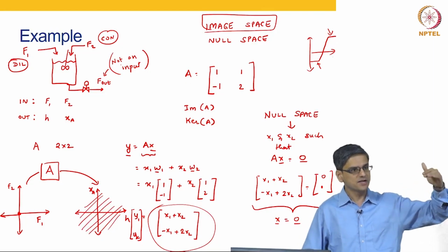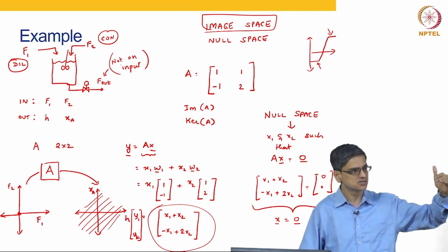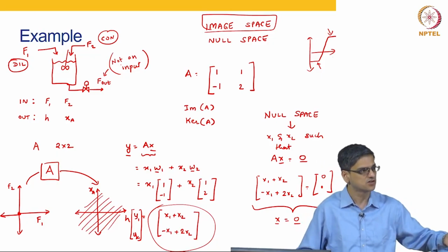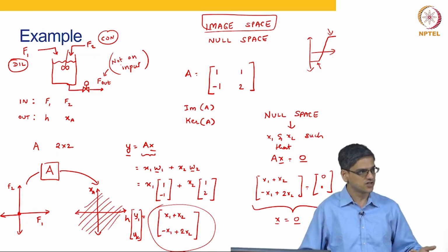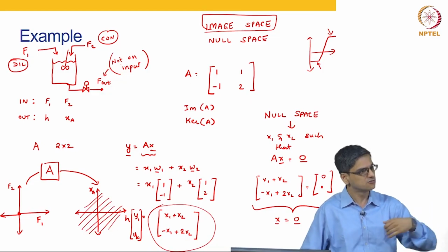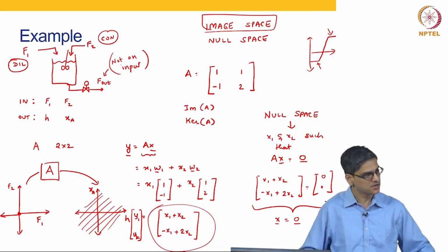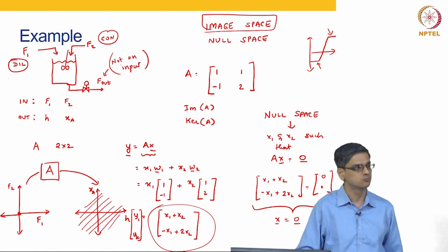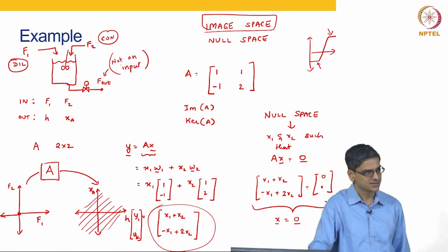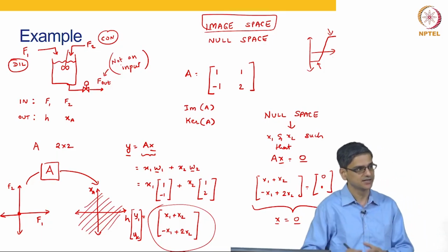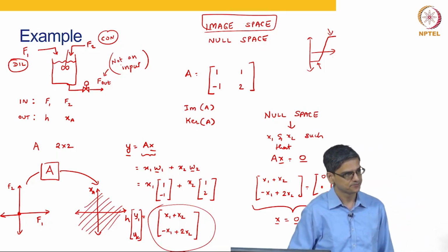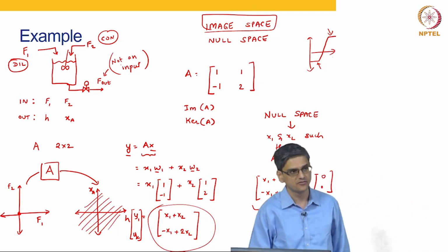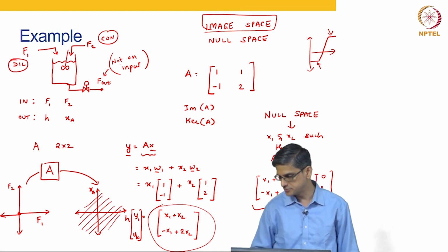If your operating condition is 300 degrees Celsius, you are not going to operate below 250 or above 350. If you go below 250 or above 350, alarms will go on and the operators will switch off and take everything in manual mode. So, your controller actually won't be allowed to go over there. That is what happens in reality in a plant. But extremely good question. We are only talking about the vicinity of our operating conditions.